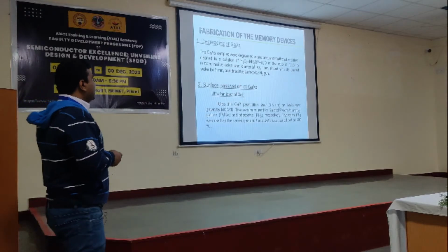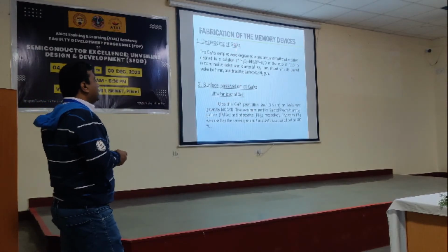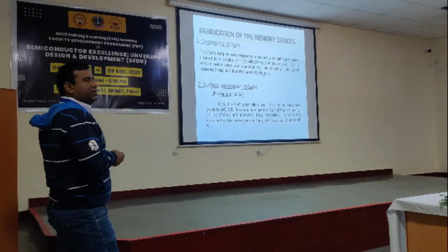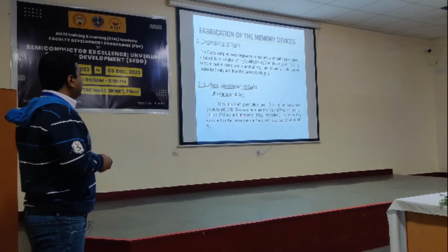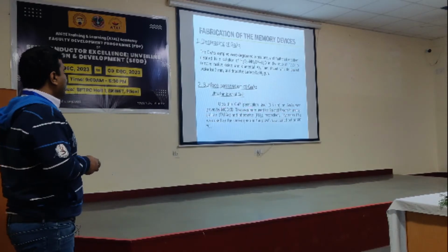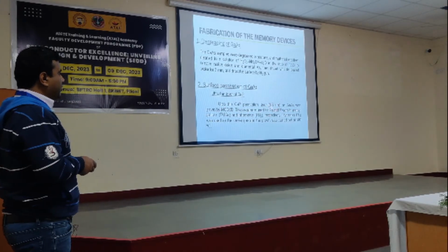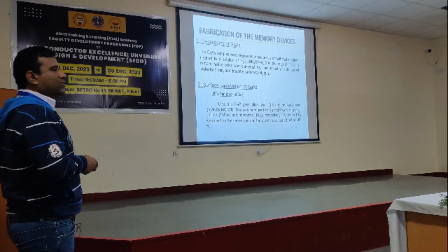Again, prior to the deposition of any layer, you have to passivate the surface in order to minimize the interface trap charge density. What is that in our case? I have taken a gallium phosphide passivation layer, 1.8 nanometer only, to minimize your surface stress.